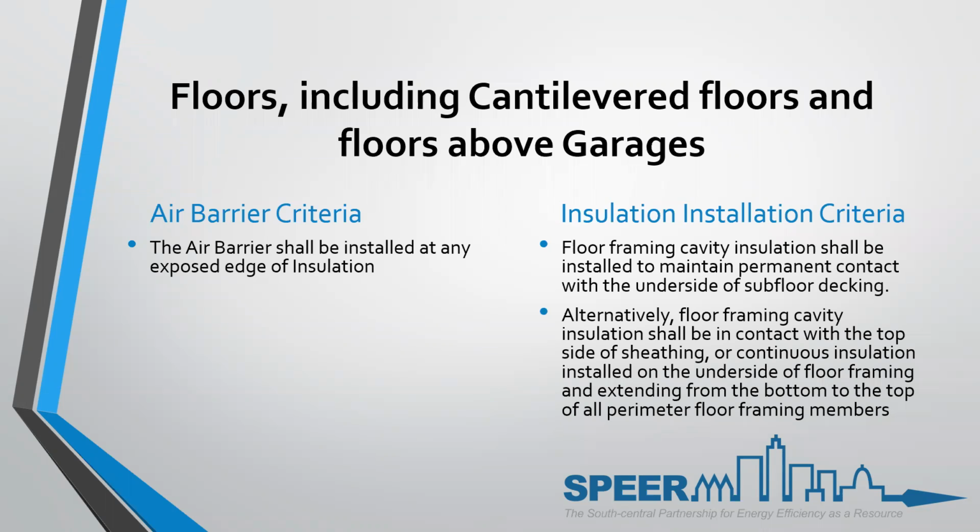If it's touching all sides because you're putting R38 and that TJI is 12 to 14 inches deep and it's fully filling it, then you don't have to try to permanently install something to keep it maintaining contact with the floor above. Most of the time it's only R19, which is code required, or it's R21 or R22, which does not fully fill it, and it must be held in contact permanently with the conditioned floor above. And that's usually tiger teeth, staples.